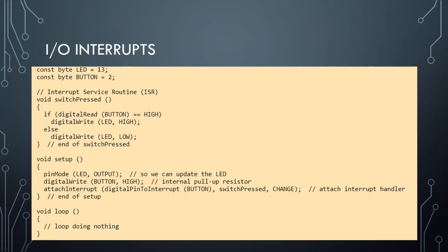And so these are just a couple ways that we can use interrupt service routines. This is a little bit different than what I just talked about. So we can use interrupts to sync up our devices, and we can also use them to quite literally interrupt a program. So there's a couple different meanings when we talk about I/O interrupts. The first is used to sync components, and the next is to create quite a literal interrupt in our program for an extreme condition, or something that we would want to suspend our program or execute some other portion very quickly because of the interrupt.